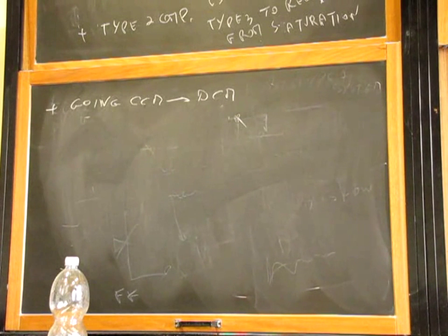If my inductor becomes a current source because it's driven by the feedback as a current source, you can put in parallel many current sources. That's okay. You cannot put them in series, but in parallel is okay. So you can have these converters in parallel very easily because they share automatically the current, because each converter has its own maximum current and they share evenly the currents.